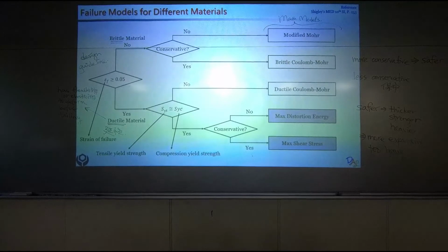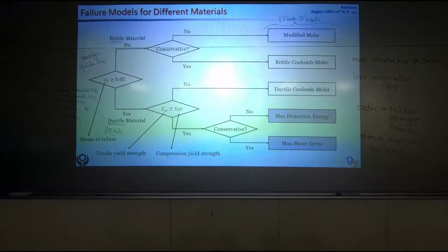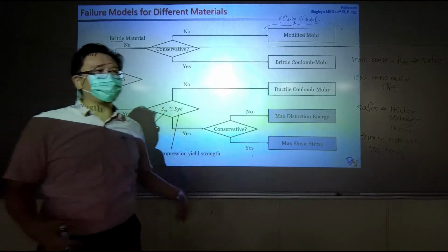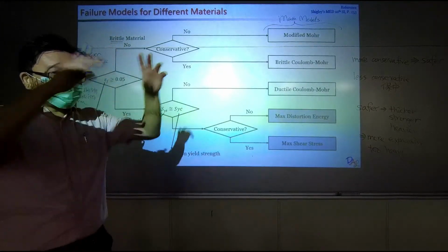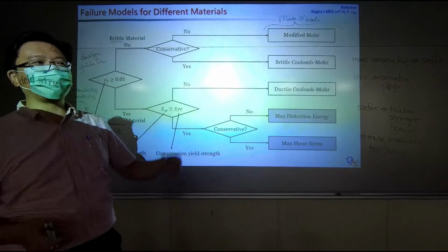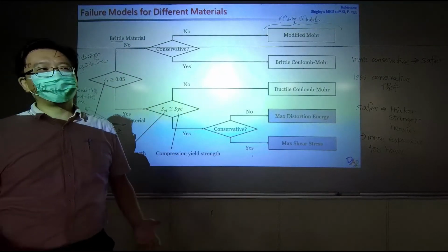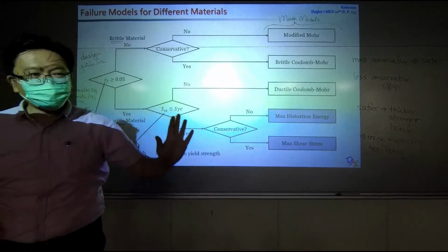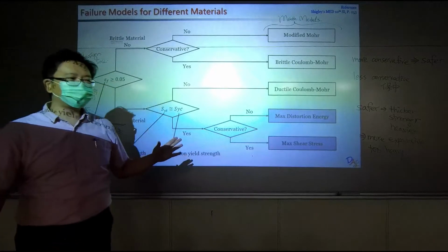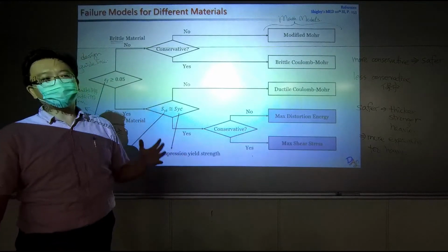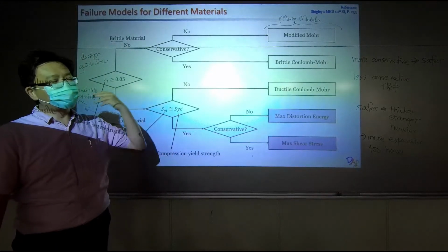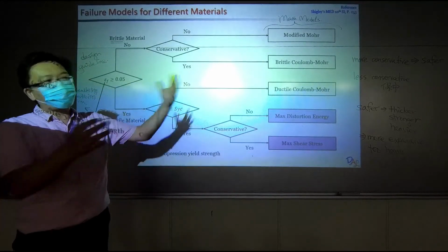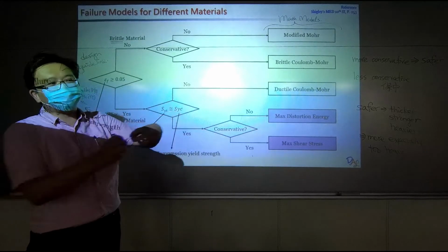Glass is a brittle material. So you never see glass being stretched, right? Only when it's very hot. Glass becomes more flexible when it's very hot. Otherwise, at room temperature, it's very brittle. So if you apply a force, if a brittle material can hold it, it holds it. But if the load is greater than its strength, it breaks directly. You don't see it stretching.